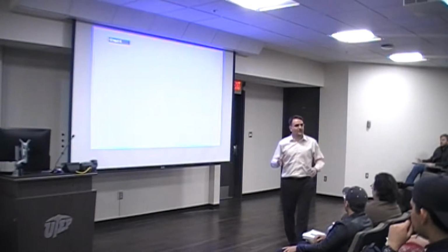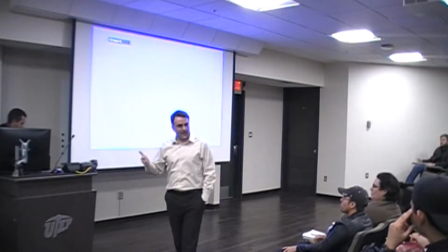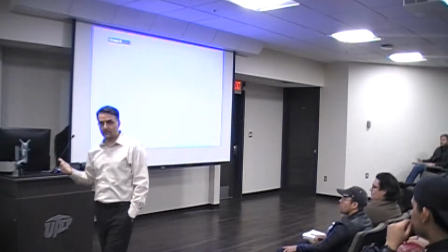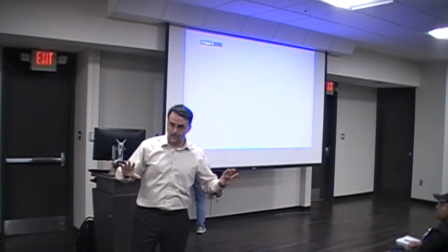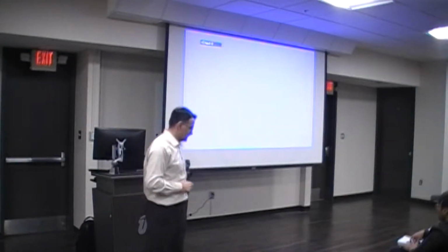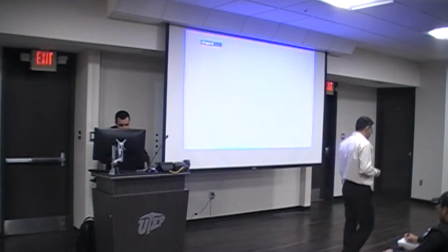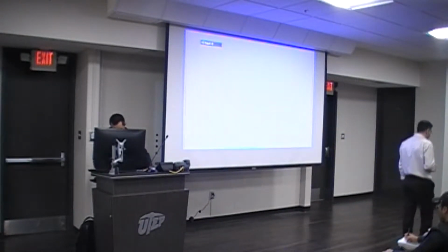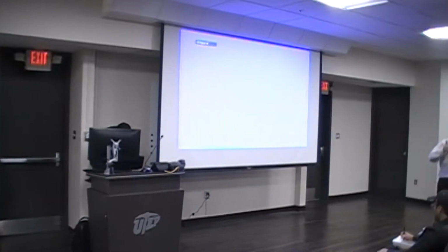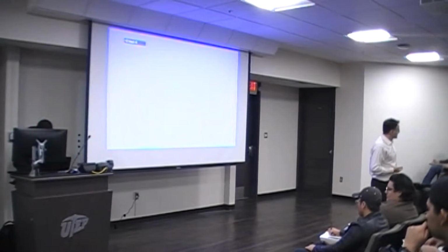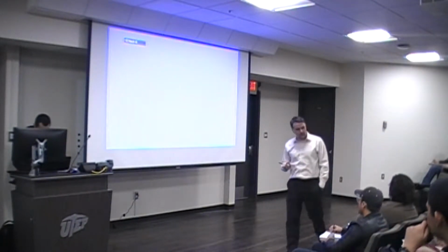So the ramification of that is soils do not have one modulus value. They do not have one stiffness property. By the way, stiffness and modulus are different entities and different concepts. You have to be cognizant of that. Unfortunately, a lot of times they've been mistaken in the industry, and that has some issues when we get into the design aspect of it. All right, so soils are stress sensitive, as opposed to what we talked about in terms of the steel. How about concrete? Do we have different values of modulus for the concrete?